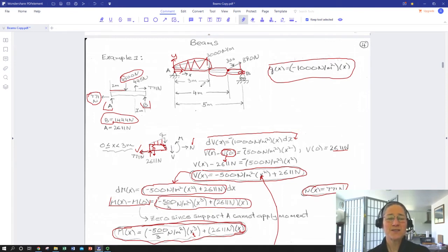So important things to do, steps to deal with these beams. Always, first, solve the whole beam FBD. Solve for the support reaction. So you may have to get some equivalent force resultants for distributed loads, figure out where to put them, then know what's going on at your supports, then start at the right or the left side, define your X however you want, and then put that cut section in static equilibrium using the fact that you're going to have internal forces in the axial shear and then a bending moment capable of being produced by the rest of the beam.